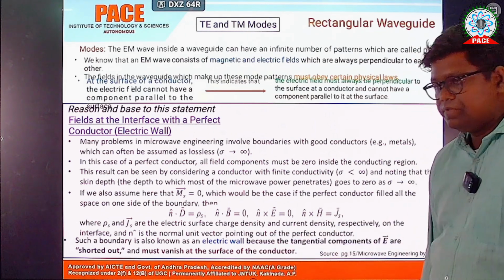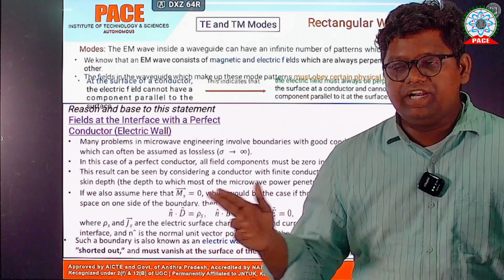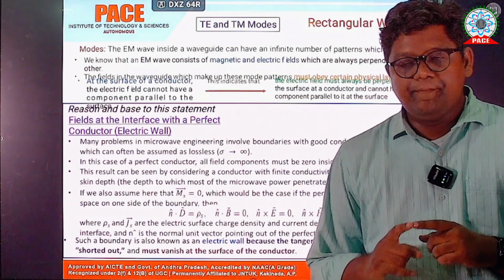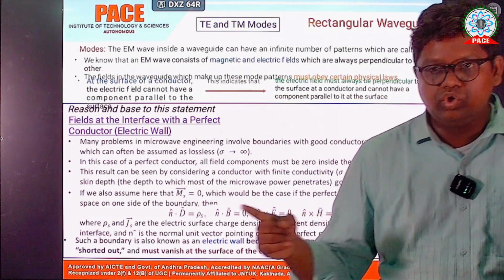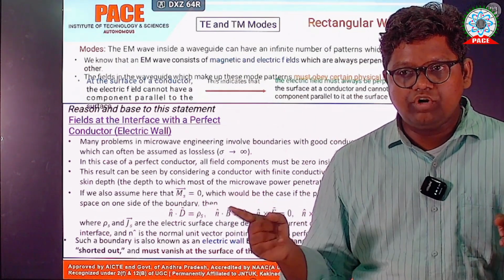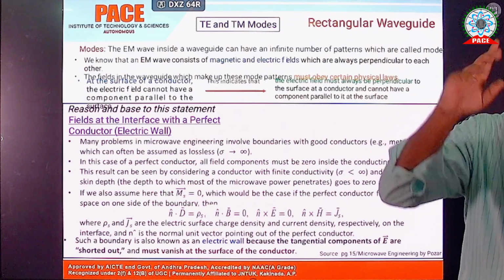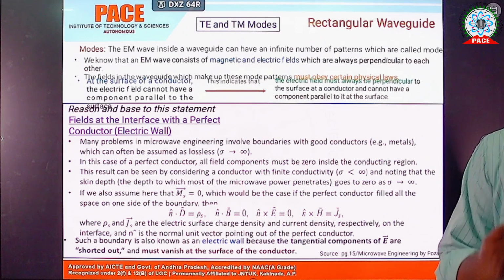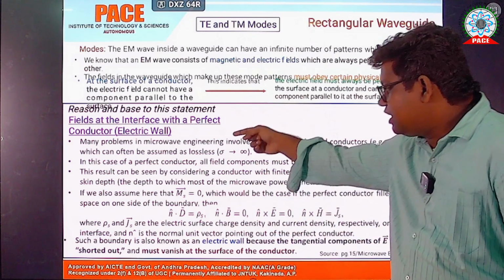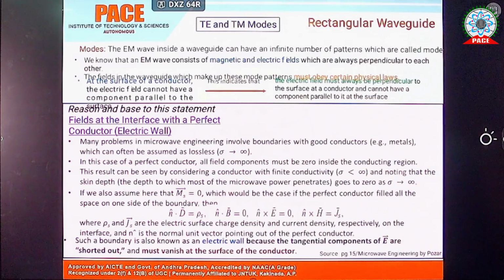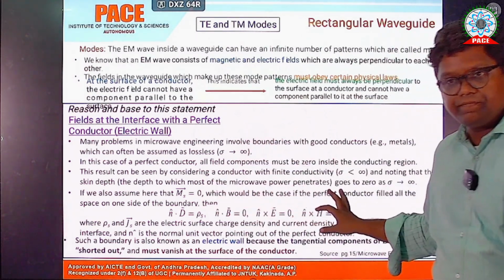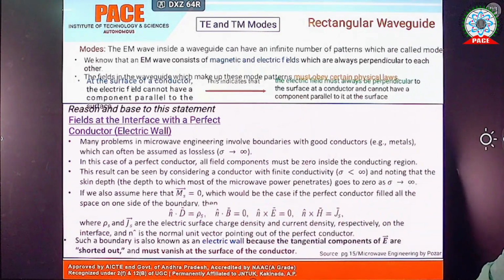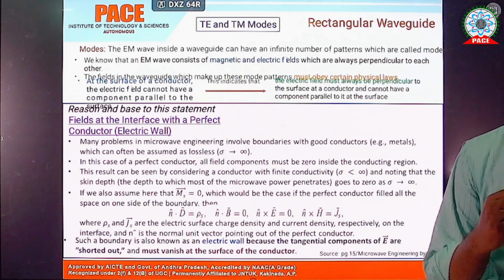If you see here, both the two walls of electric fields will have a perfect electric condition, and a box consisting of 6 planes, whereas 2 will be coated with perfect electric conductor, 2 will be coated with perfect magnetic conductor, and the remaining two will be ported for a source. So this statement justifies that we will be inserting electric field distributions here, and in the remaining 2 we will be inserting magnetic field distributions, and the remaining walls will be used to give the port.